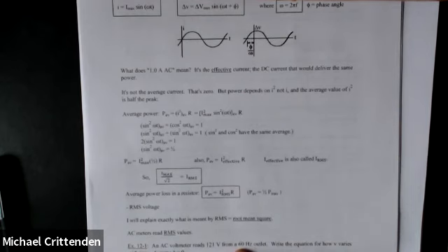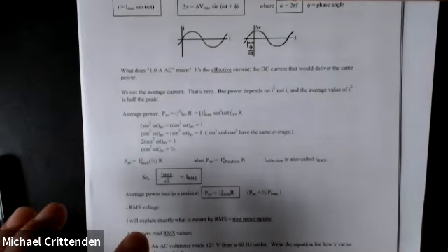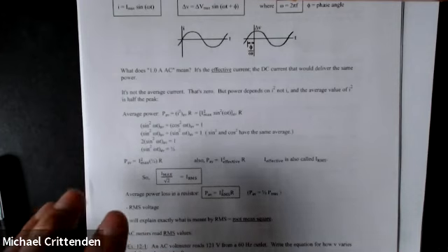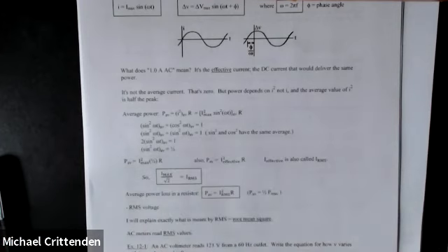On the other hand, I think I mentioned this when I was doing Lab 8, the one with the oscilloscope where we were comparing the signals. This one's 60 hertz, and matching it up and getting the circle on the oscilloscope screen and all of that. I think I mentioned then, they have to be very careful about getting exactly the right frequency, because if you've got one power plant that's running at 59.9 hertz and another power plant that's running at 60.1 hertz, and you dump all that electricity in the same grid, you're going to get beats.